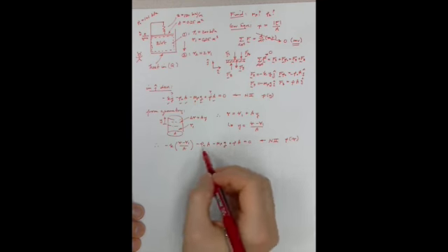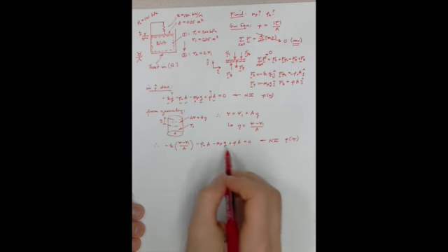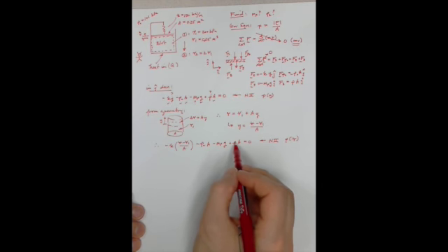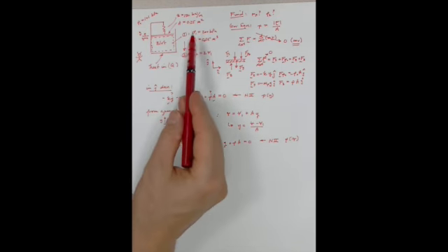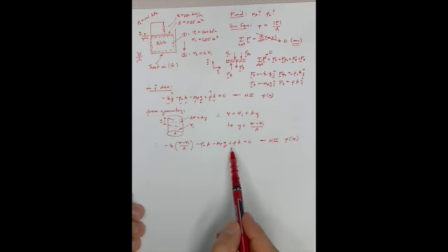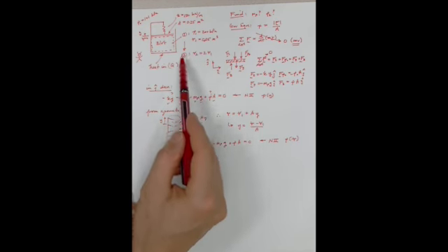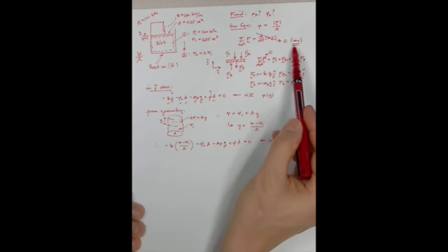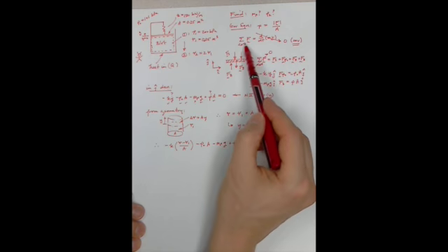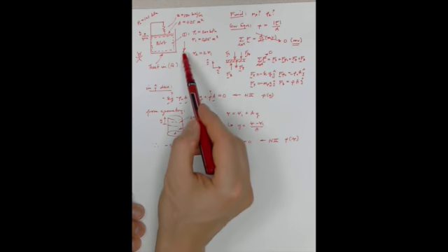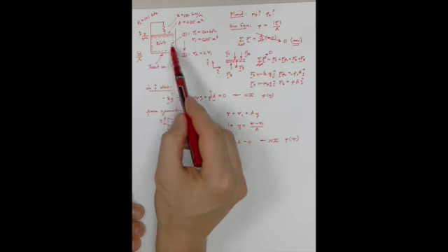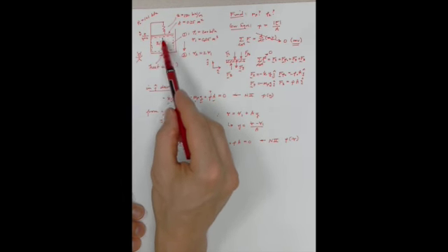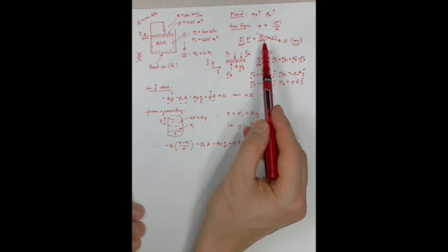So what we probably want to do is consider that first. I've not assigned this P to be either P1 or P2 or any other P. It's good for all the states in between 1 and 2. Why? Because we assumed that this process was reversible, which means that Newton's second law tells me that the sum of the forces equals 0 at every state, 1, 2, and all the states in between, because a blob is what's causing this motion to occur, not a force imbalance.